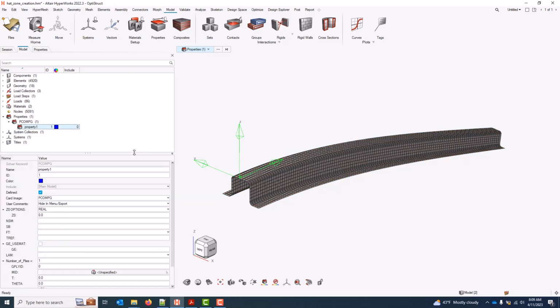I'm going to define 2 zones so that this model is analogous to our ply-based version. The first takes the full 8 plies on the left side of the screen right here. The right has a ply drop of 2 of the plies and is just the plies on the right side of the screen.